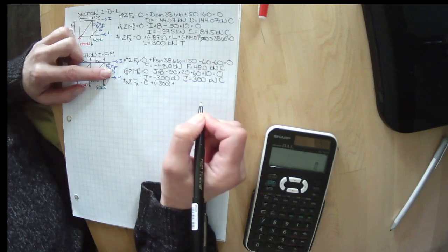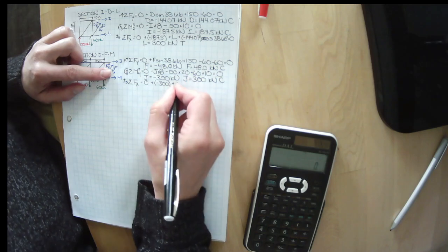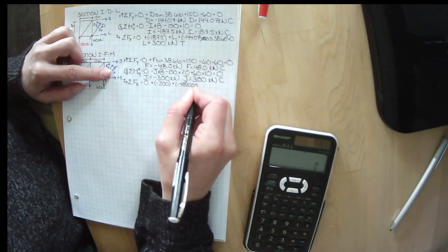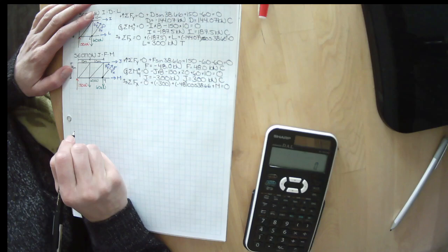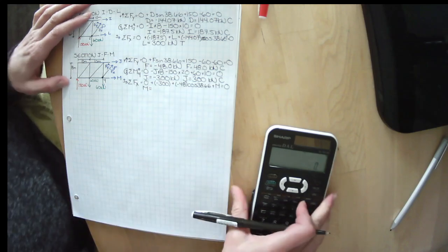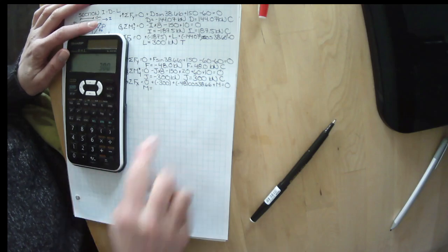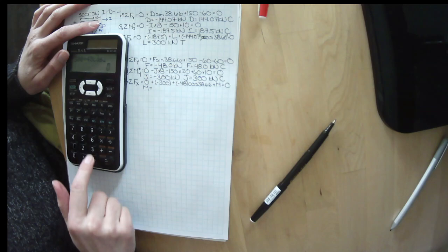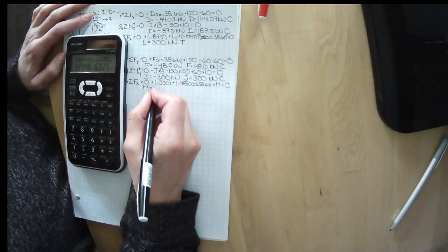But we know that Fx is F times the cosine of 38.66, and our F is minus 48 times the cosine of 38.66, and we've got plus M. We can rearrange this and solve for M. We bring 300 over, and it's positive, and we bring that over, and it's positive, so plus 48 times the cosine of 38.66, and we get that M equals